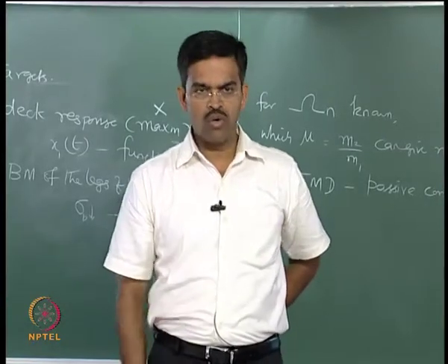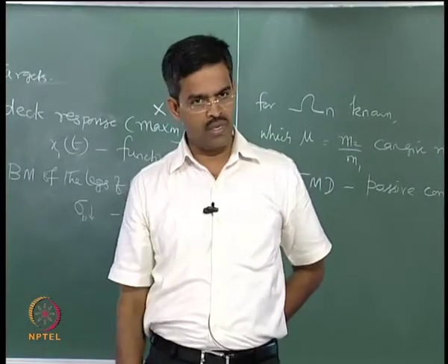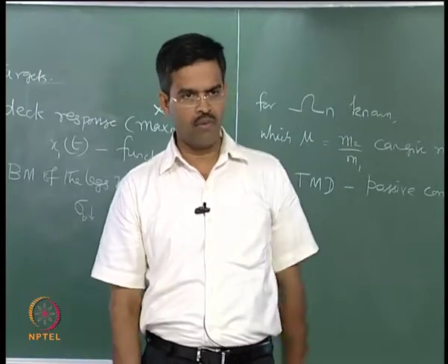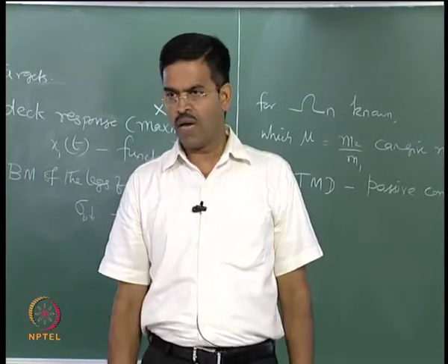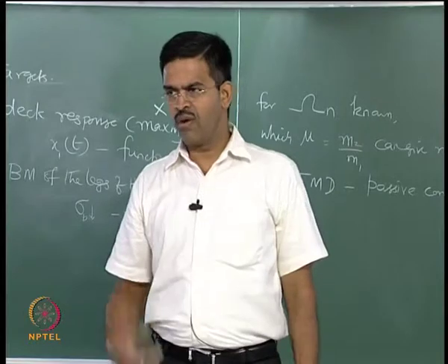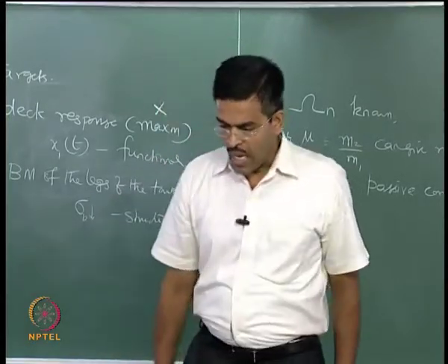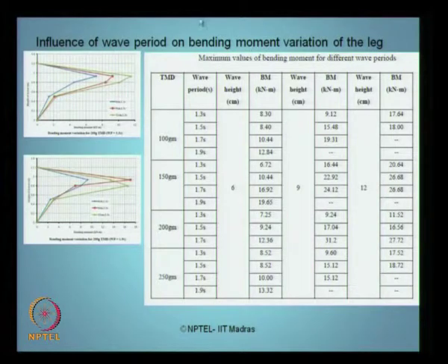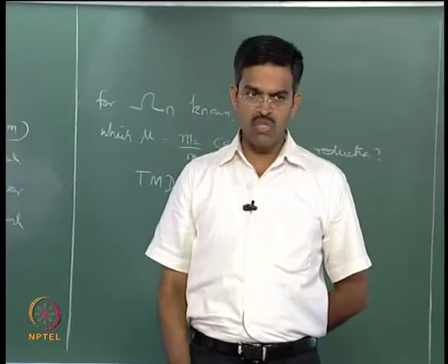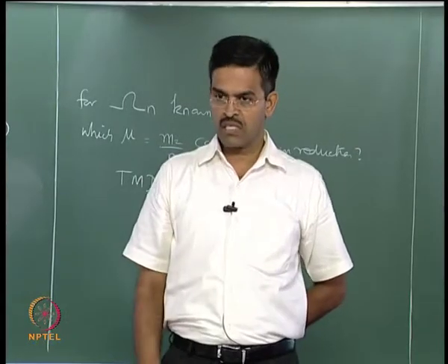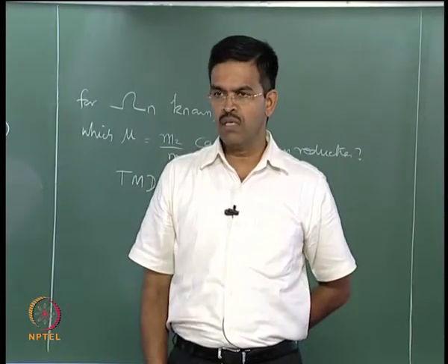Without TMD also the same scenario was notified. I will show you a comparison later. So, the bending moment will increase with the increase in wave height for the same wave height for wave periods. Qualitatively it is not, and also there is no apparent shift of the maximum bending moment because of TMD available. The location where the maximum bending moment will occur on the leg remains almost same. So, the critical cross section with and without TMD remains same.